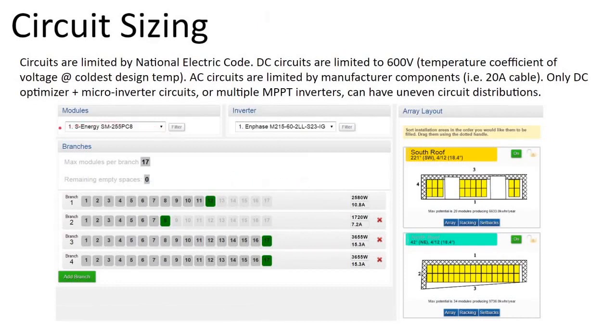And so here we've selected a solar panel and in-phase microinverters. For this particular microinverter, the maximum number of modules per circuit is 17. And right here in Solar Design Tool, in the design software, we're being limited to the microinverter's capabilities.